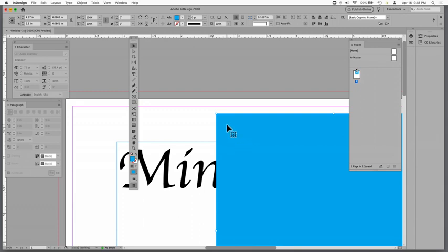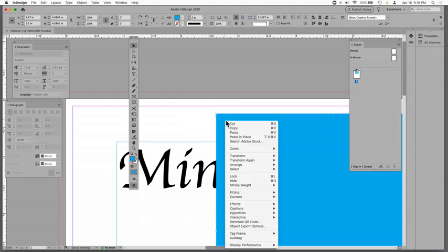So in this case, I'm going to select the box, right click on top of the box, and then there's a handy thing called Arrange. The cursor is content aware, so it knows that this box is at the front. If it was in the middle of the stack, it would actually say send to front or send to back, or send backwards or send forwards.